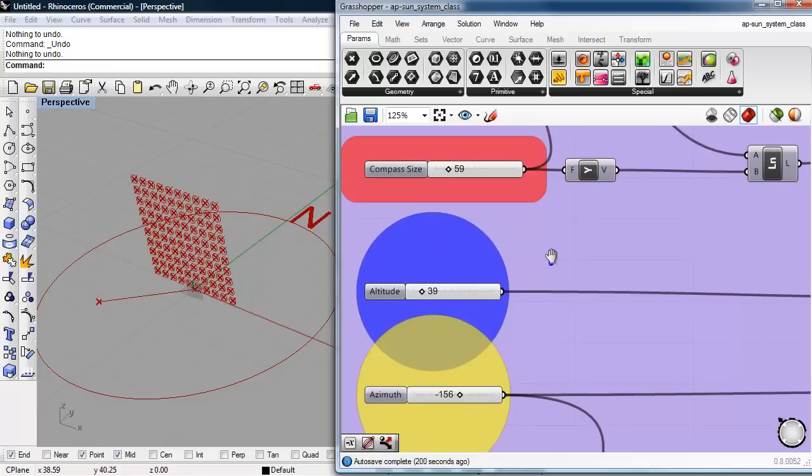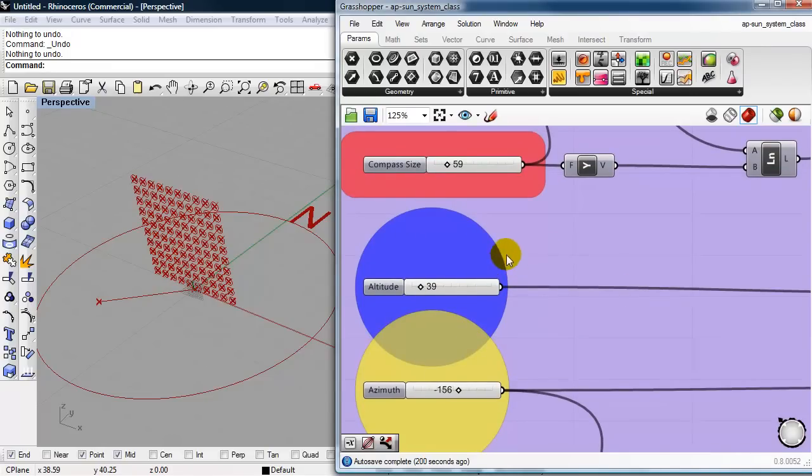And in this tutorial we're going to look at using a daylight system that's composed of an azimuth angle, so you see there's a north arrow, and we're going to use a winter sun condition. So as I move the daylight around to the south, I want to maximize solar heat gain for passive heating. So I want the circles to get larger. So if I lower the azimuth back to north, the circles are getting smaller.